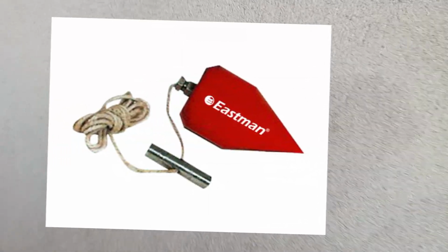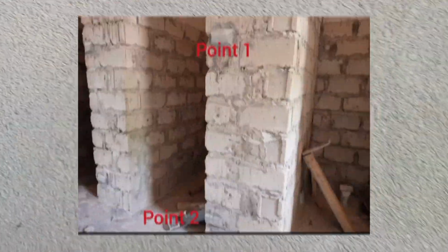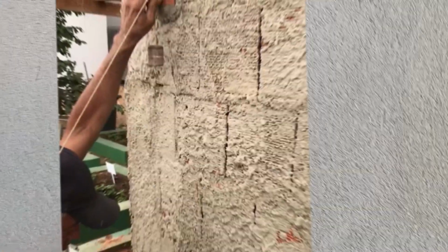So again, when we are doing the plaster, remember I've said for us to achieve the verticalness of the wall, the plumbness of the wall, there is a tool that we use called a plumb bob. From your 3 points that you had done on the wall, that is to make sure the wall is leveled, at the first point you will put your plumb bob, going downwards to the down point, and make sure that your plumb bob settles as required. Then you will know that that wall of yours is actually straight, or it is actually plumb as required.